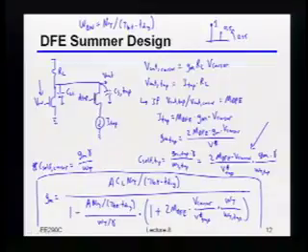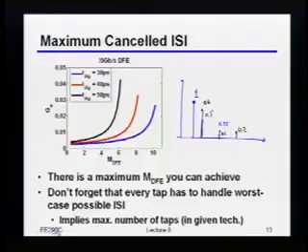Okay? So the key insight here is that, from a practical standpoint, this tends to mean there's a maximum number of taps that you can do in any given technology at a given data rate. That's practically how you will tend to use this the most.